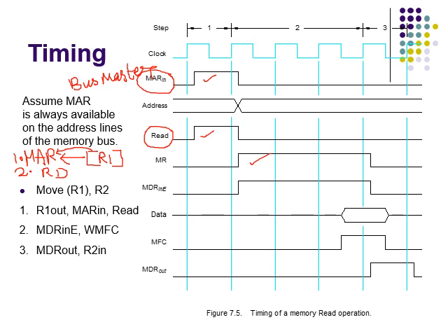So action 3 and 4 can also be combined by activating control signal MDR in E while waiting for a response from the memory. Thus, the data received from the memory are loaded into MDR at the end of the clock cycle in which the MFC signal is received.